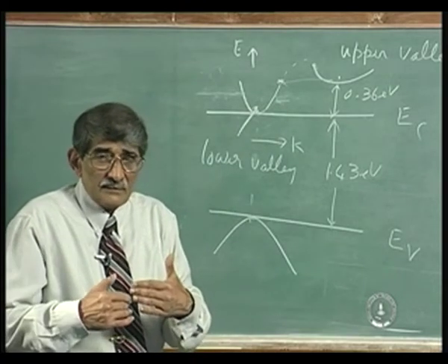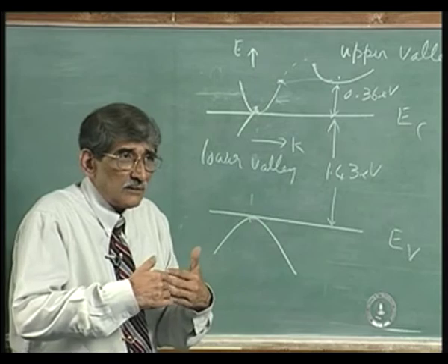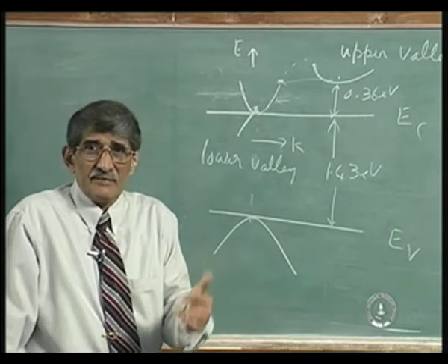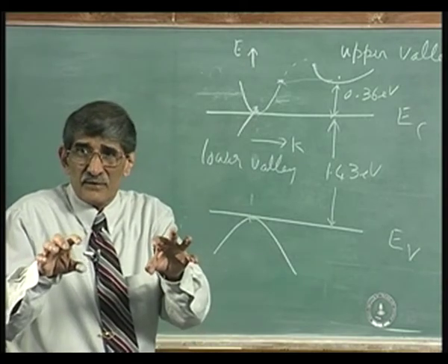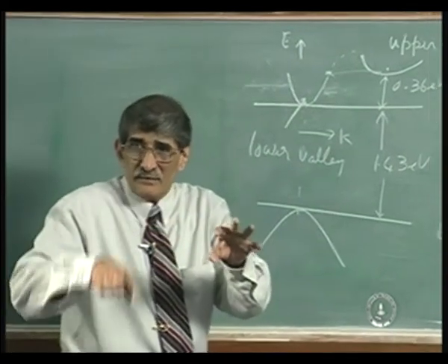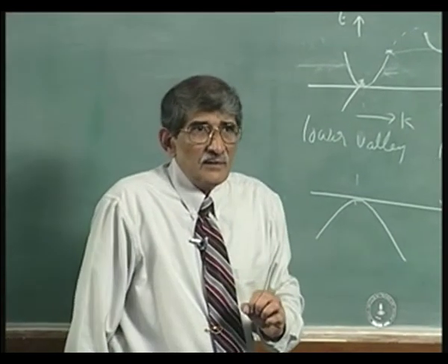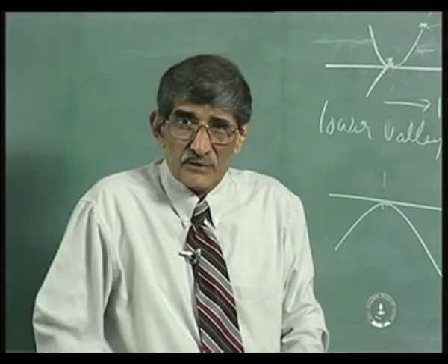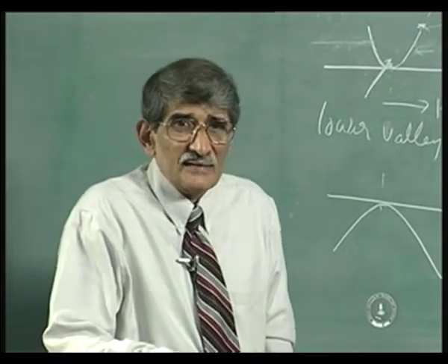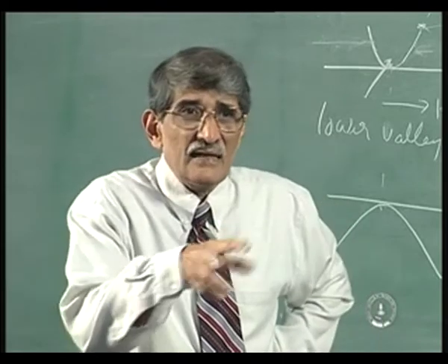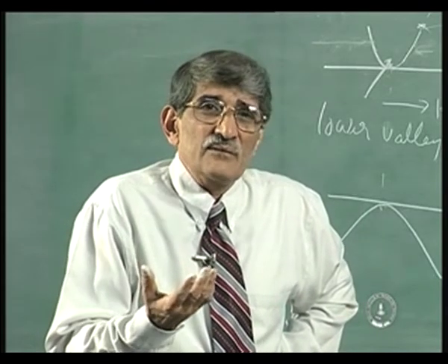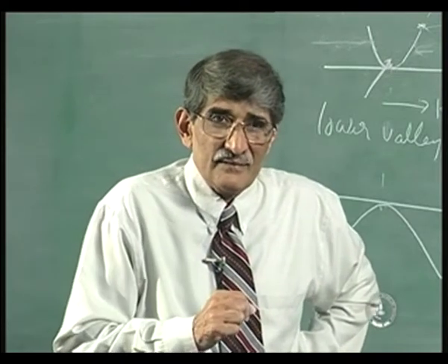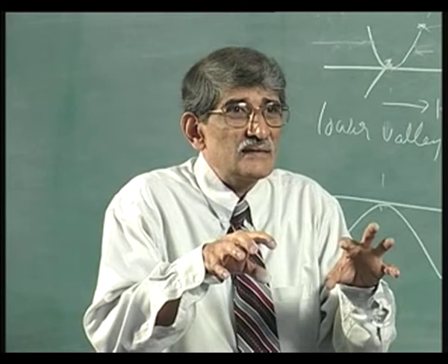In silicon, the electron goes through the potentials due to the atoms. There is potential variation because of the atoms. As it goes to the nucleus, between the nuclei, it goes through the potential peaks and down. That is the only thing that is seen by the electron which is moving. That is the effective mass due to the potential changes. If there is no potential change, if there is no field within the atoms, the mass would have been the mass of the free electron. The effective mass comes up because of that potential change due to the charge in the nucleus.